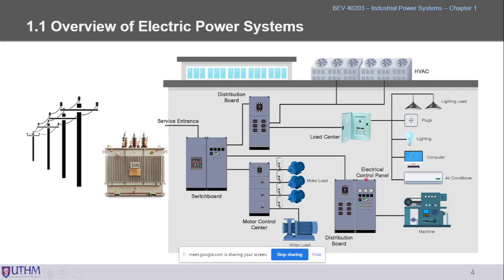Okay? So that's why, if it's a huge pump, we have to lead the cables directly from our incoming, the incoming from the switchgear directly. So we don't tap the power from, let's say, the MCC or the distribution board here, right? That means it needs more protection, because this one will draw a lot of current, and it might disturb the rest of the load.